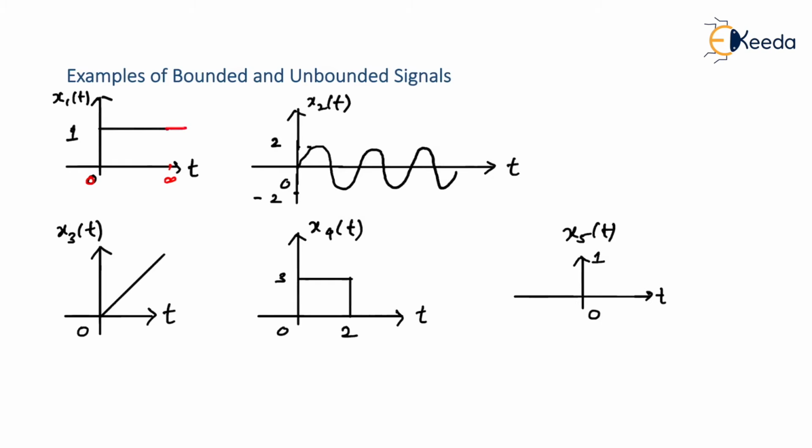What is important is amplitude everywhere. For t greater than 0 amplitude is 1, and for t less than 0 amplitude is 0. So amplitude has only two possibilities, either 0 or 1, and at t equal to 0, by Gibbs phenomenon, we say it is half. But the point is, everywhere amplitude is finite, and therefore such a signal is called a bounded signal.